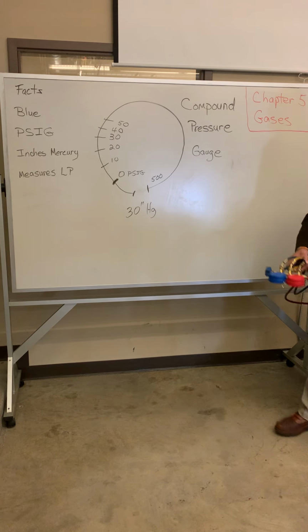And this is when you hear that term, they're vacuuming the system. We're removing that atmosphere. We're removing the air from a system, a sealed mechanical compression system like you see right here. Why do we do that? Because remember, there's a relationship between pressure and temperature.